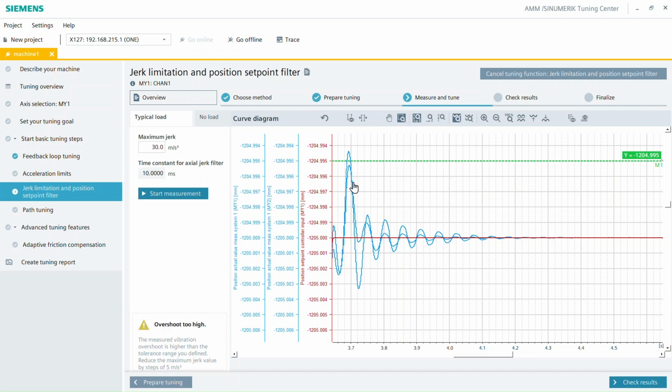In the arrival, you'll see several effects, like friction and the transition from standstill to motion, but also dynamic effects. Here, we focus on the dynamic effects related to acceleration force and how strongly it's applied. If acceleration is applied immediately, meaning with infinite jerk, the axis mechanics get a strong impulse, which usually causes a high vibration amplitude. By looking at the arrival and the vibration in the plot, you can decide whether to reduce or increase the jerk value.